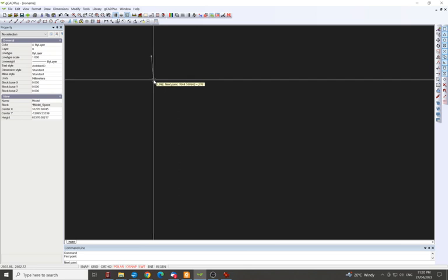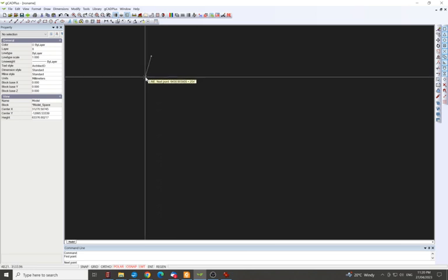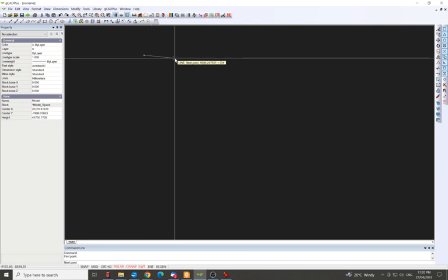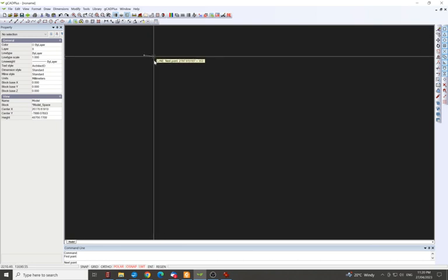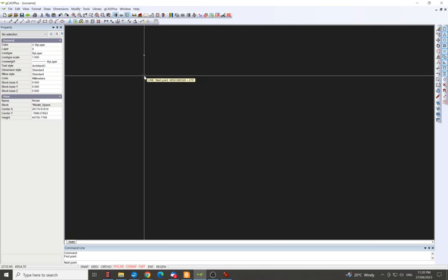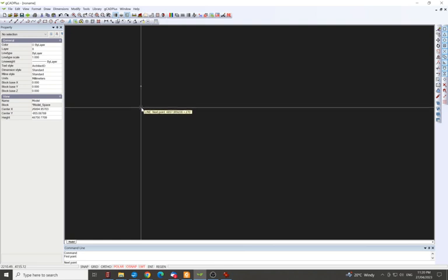And we're going to see how it locks on with polar tracking. So this is going to lock onto, what would that go? So that's 90. What have they got here? 0, 90, and that's 270. So 270 degrees. We're just going to go straight down. We can go up if you want. Doesn't really matter. I'll just tend to go down. And we're going to make this the post.